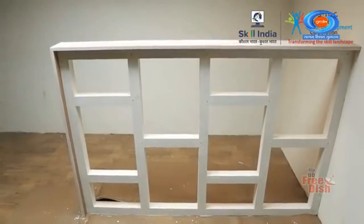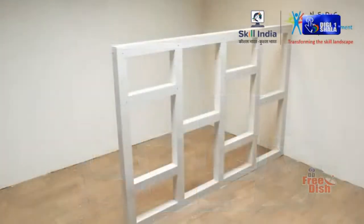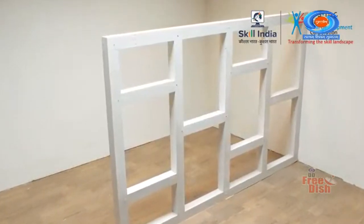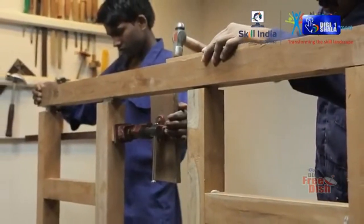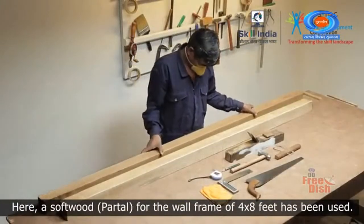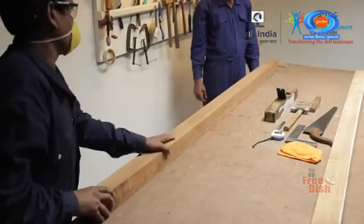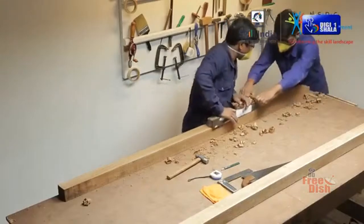Start by examining the work drawing for dimension and design of the low-height partition. The simplest way to make partition walls is to construct a framework to which plywood can be fitted on each side. Traditionally, timber is used for making the framework. Here, a softwood of 4 by 8 feet has been used for the wall frame. Always use wood of slightly bigger dimensions. This gives you margin to true and smoothen the wood surface.